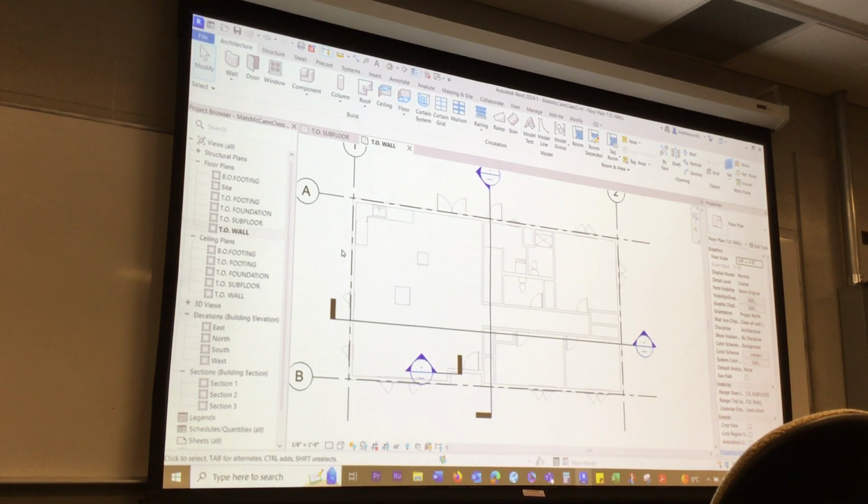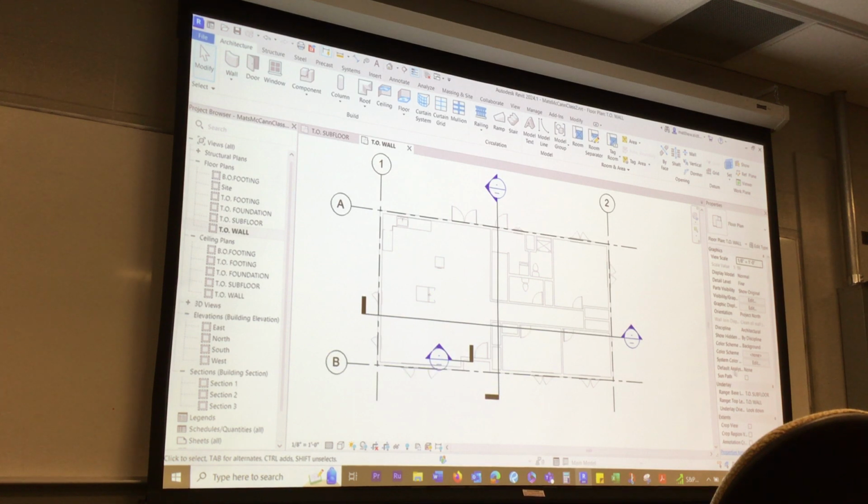I can't seem to select my DWG in top of wall view. I can select it in other views. Like I can see the DWG, but it's not saying that it's something I can click on. Just let go of some stuff and change the view back and forth. We may settle it when you go check your view range.